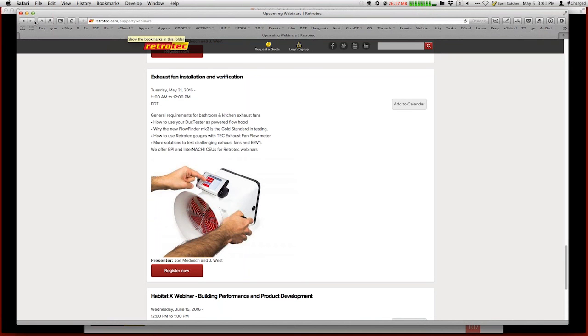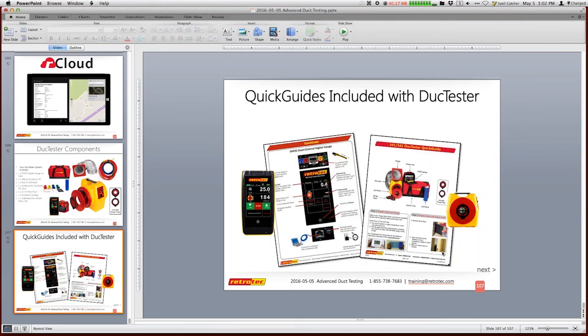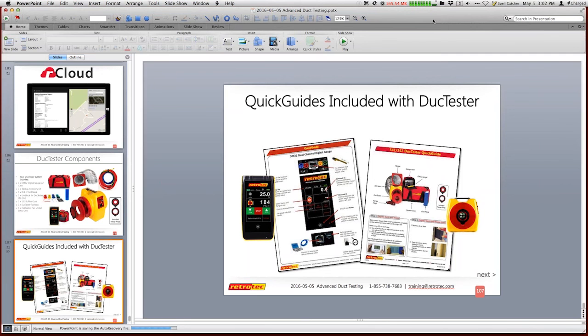So Samantha asked, essentially, is it not possible to seal ductwork to the point where it affects the envelope in a negative way? That can be correct, but it also can be a challenge. Here's one of the issues that happens, which we did a webinar on static pressure. Even though it's advanced, there's only so much you can do in an hour. If I overseal a system that was used to having what it thought was normal leakage, and then suddenly I sealed it, I increased the static pressure in the system.